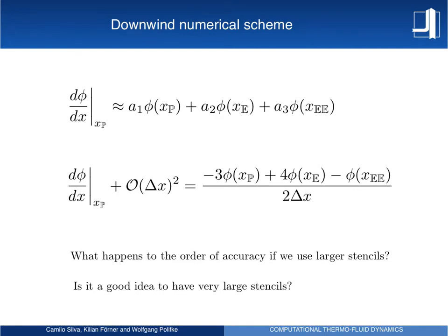Then, if you want to avoid dispersion or dissipation of the acoustic waves, you may want to have very high order of accuracies in your numerical scheme. Okay, very high, I mean something like 6th to 10th. So depending on the physical problem of interest, you will use the proper numerical accuracy you need. This is one thing.